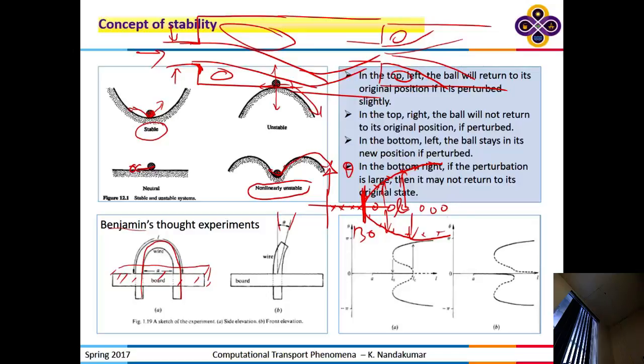and then extrapolate back, for example, one way of doing the experiment would be, in fact, this is what we did in our paper, measure the length of that wave. When it is symmetric, the length of the wave on the top and the bottom should be the same. But when it is non-symmetric, there will be a difference. So the difference will go to 0. So we plot the difference against the Reynolds number at various values of Reynolds number, and then you extrapolate it back. You get a few points here, and then extrapolate back. In an experiment, you'll get the same value that is predicted by theory.